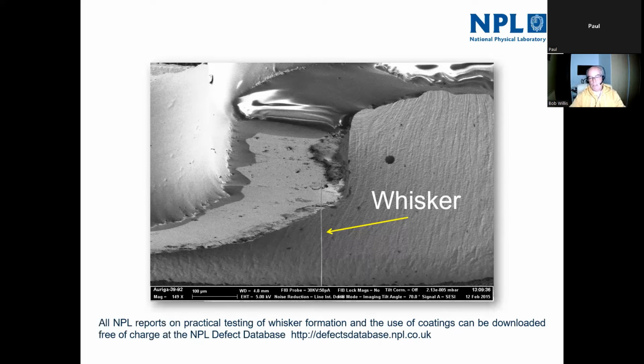And if you look at this SEM image, scanning electron microscope image, you can see that lighter gray surface close to where the whisker is making contact, there's no coating there. So again, it's not necessarily on the surface. You've got to be looking around the whole of the lead to see that we've got some form of coverage. It depends obviously on the application you want. But tin whiskers certainly created lots of industry issues, and coating is one of the things that reduces that. The interesting thing is that tin whiskers can actually punch holes through coatings, and the only one they don't generally poke holes through is silicone coatings. So again, just a little bit of side information for you.